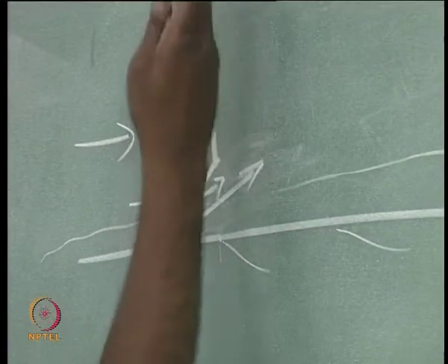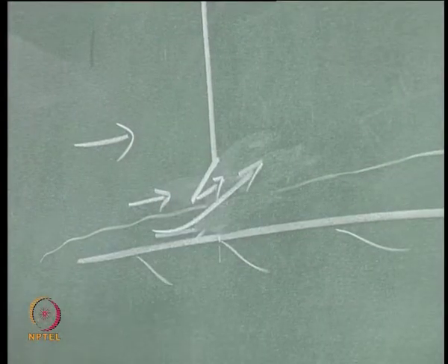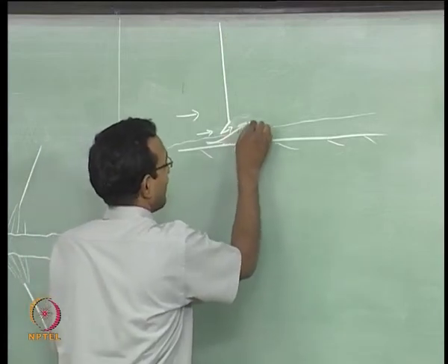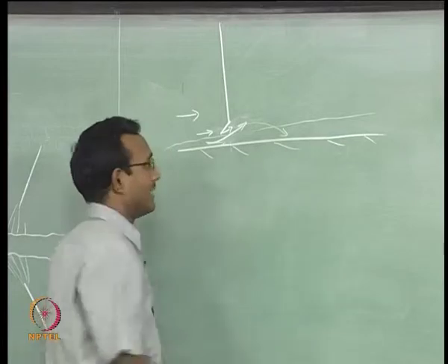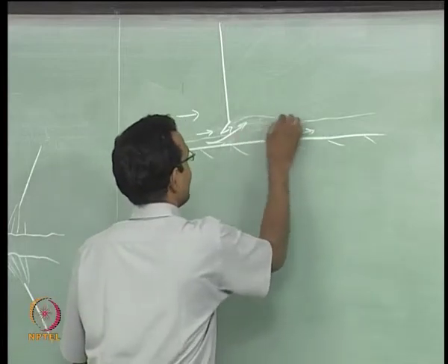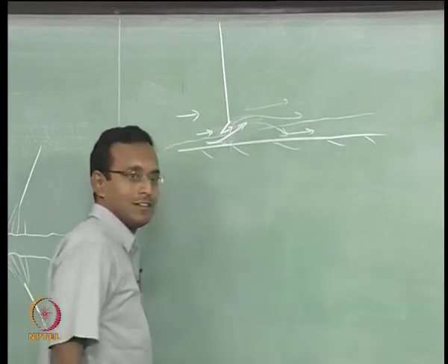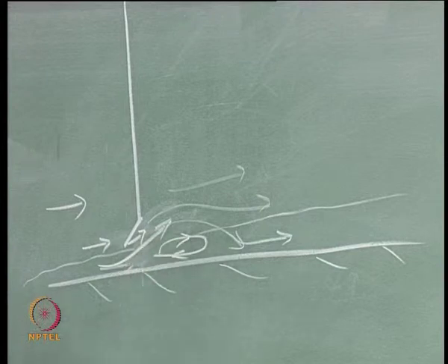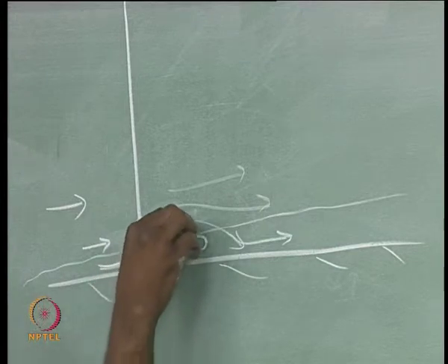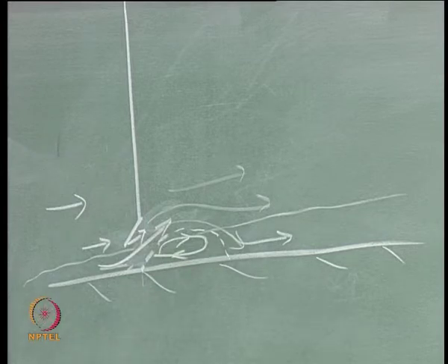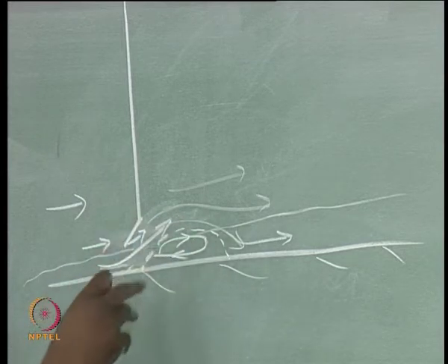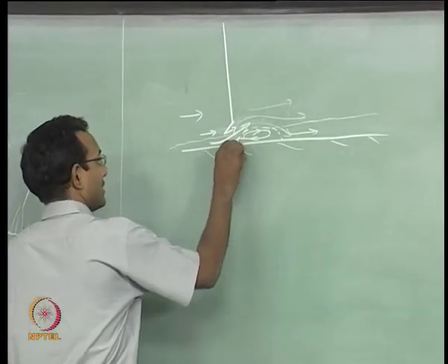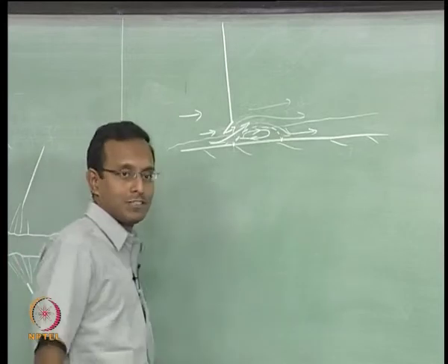But after some time the flow is going to be very low velocity, slow speed flow, and it so happens that the boundary layer will reattach after some time, and then it will again go like this. It is low velocity, it is decreasing velocity, it is just going to go like this. So, now what happens is there will be a recirculation zone sitting here. There will be what they call a separation bubble formed here. That dotted line is the one streamline which is separating the fluid that is circulating and the fluid that is moving. That is your stagnation point here and here, separation stagnation points.